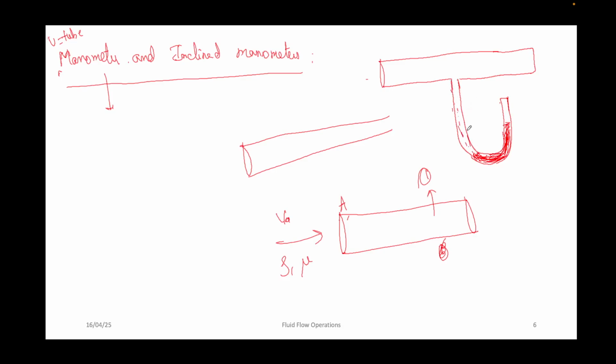Okay, so the difference between, so let's say this is height h1 and this is at the same location. Okay, so let's say this is h2. So if you want to calculate the pressure exerted or the pressure inside this pipeline, you just have to measure the height of this limb, okay, height of the liquid in this limb, and multiply it with density and gravity.